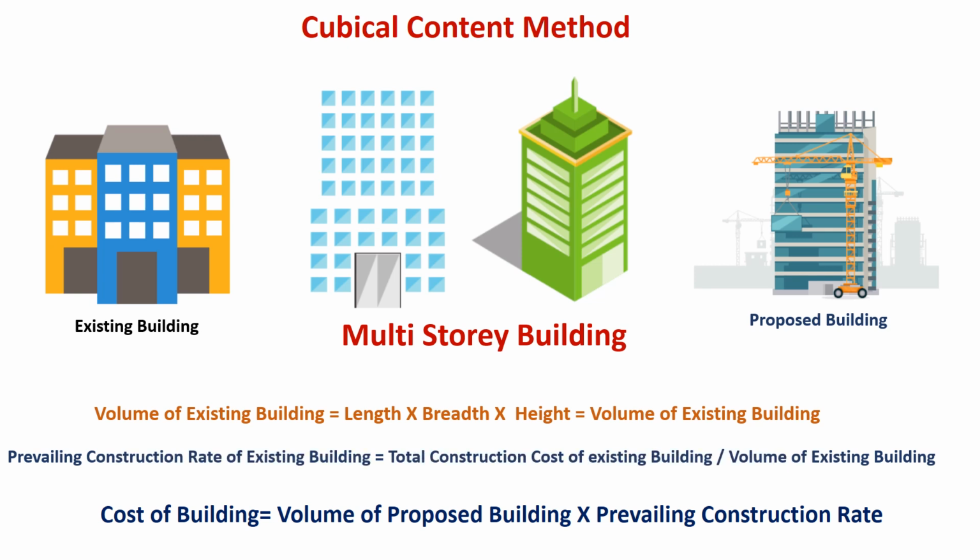Then we can find out the prevailing construction rate of the existing building: we inquire about the total construction cost of the existing building and divide it by the volume of the existing building. So you get the construction rate of the existing building.